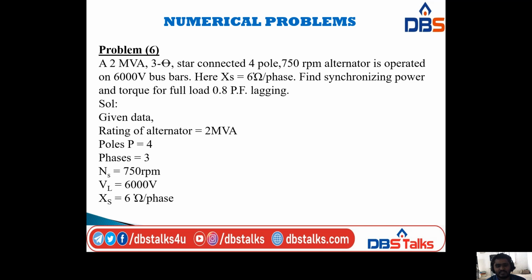This is for the 3-phase, and after that we will convert this into single phase, that is 6000 by root 3. Okay, next Xs, the synchronous reactance, is equal to 6 ohms per phase. By using all this data, we have to calculate the synchronizing power and synchronizing torque.